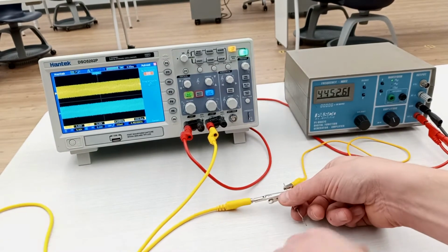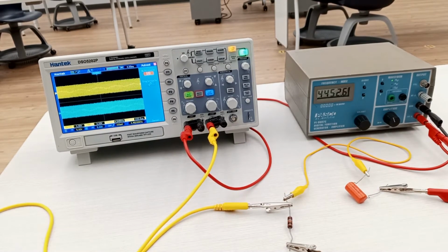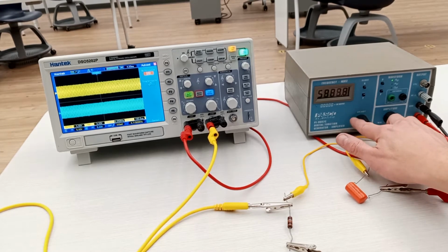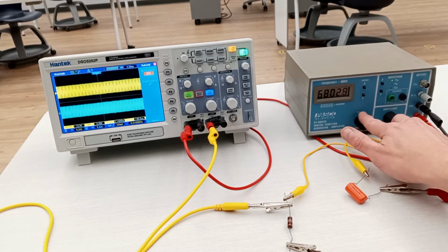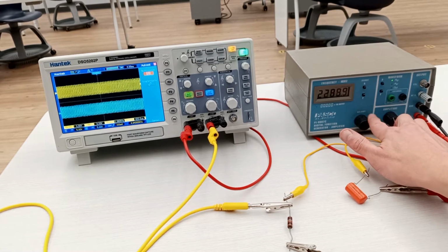The voltage across the resistor behaves in the opposite way. The resistor tends to respond quickly to changes in voltage, but then its voltage decreases with time as the capacitor charges up. So as we can see, low-frequency signals are blocked and high-frequency signals get through unattenuated. So this is a high-pass filter.